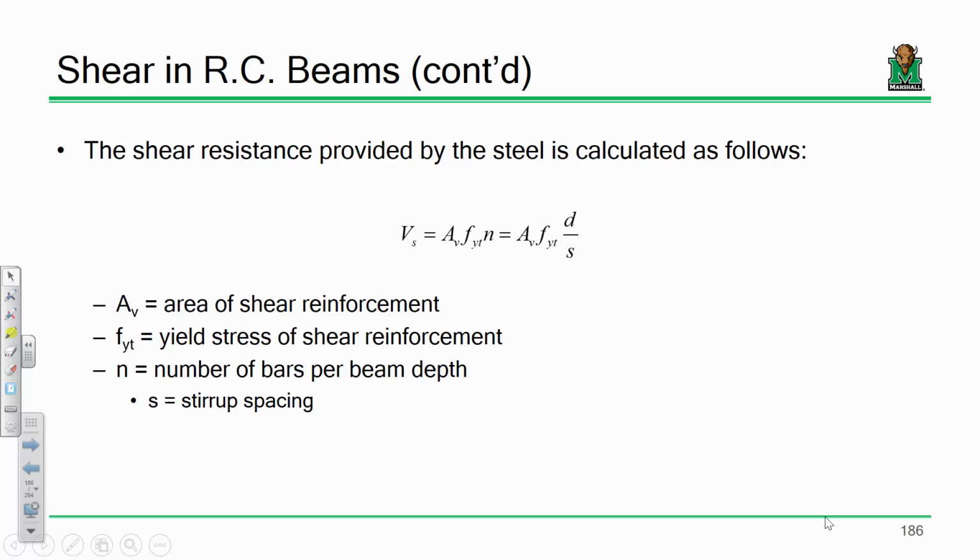What about the shear capacity provided by the steel? And when I say the steel, I mean the stirrups. I'm talking about those hoop sections going across the span. Now, this is where things get a little new. I want you to pay attention to some of these terms. It's not the math that's complicated. It's figuring out the right terms going into it.